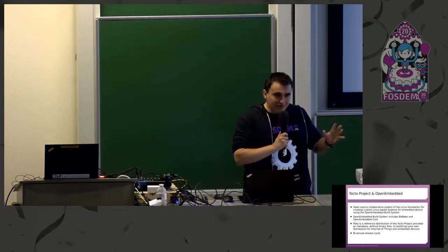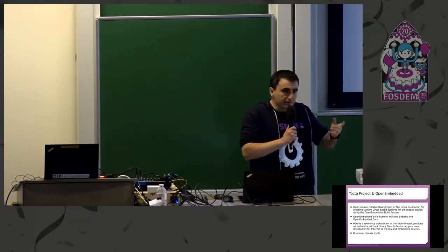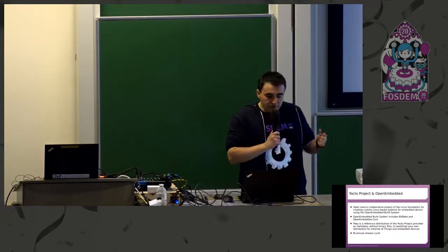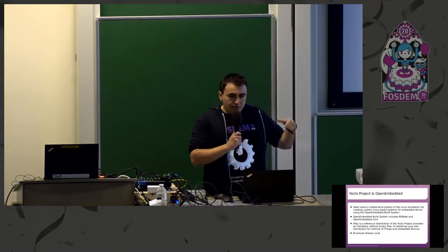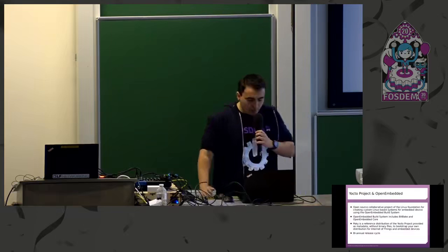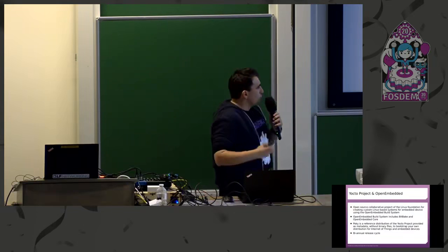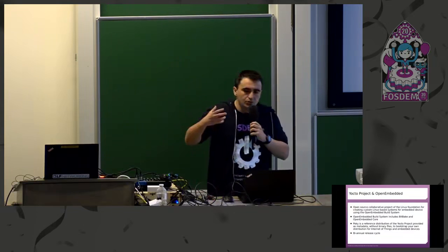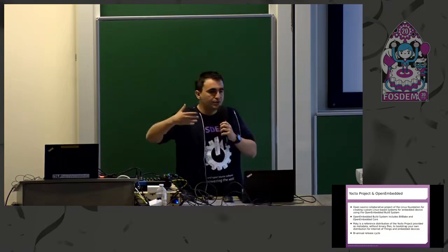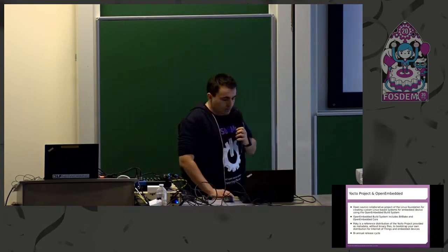So the Yocto project is an open source collaborative project of the Linux Foundation. It is designed to build custom GNU Linux distributions used in a variety of industries. The Yocto project has chosen the Open Embedded build system, which includes BitBake and Open Embedded Core. Poky is the reference distribution of the Yocto project. It provides metadata, so you don't actually start from scratch, but you already have a list of recipes and layers on which you can have a quick start, and after that you can continue customizing Poky.